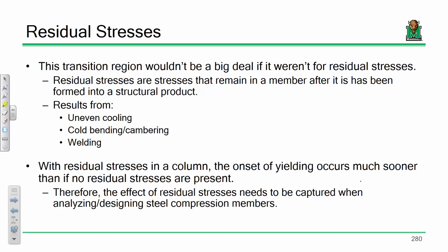Well, the short answer for what a residual stress is: any stress that is locked into an element or a component from the fabrication process. So let's go back to how they would manufacture a rolled I-beam. You've got this big pool of molten metal, right? You cast it into a big steel billet, like a steel near net shape, and then they place it under those super high capacity rollers, and they sequentially flatten this plate and flatten this plate a few times until you get a shape that looks like this, right?